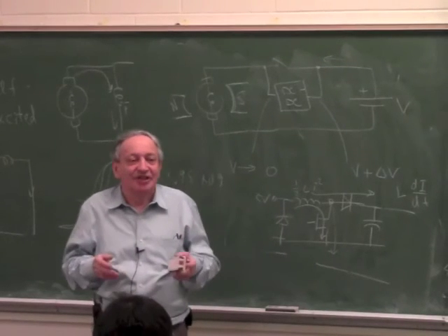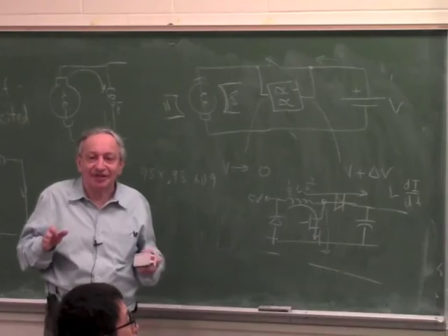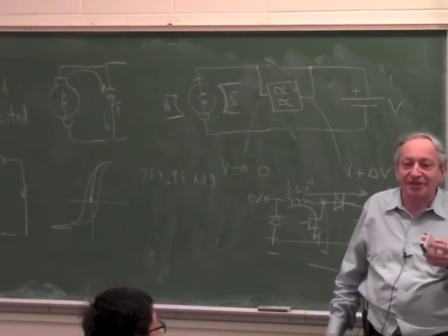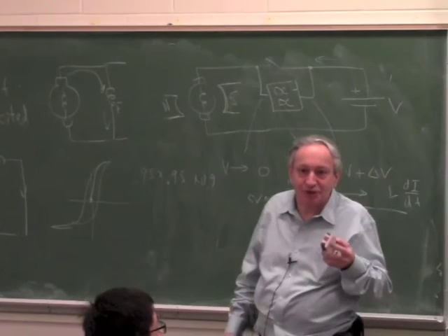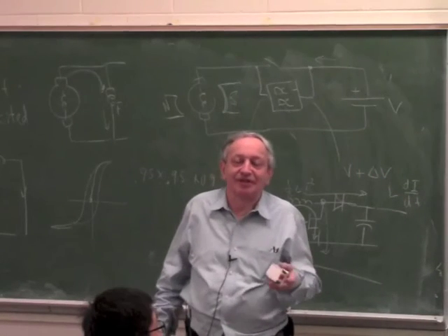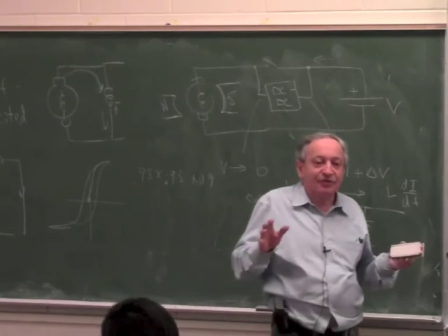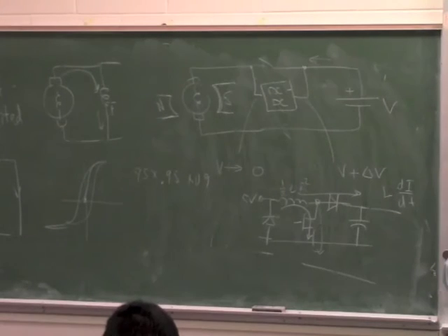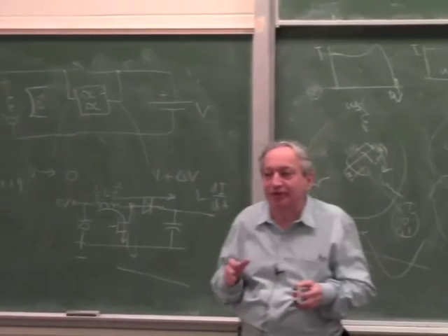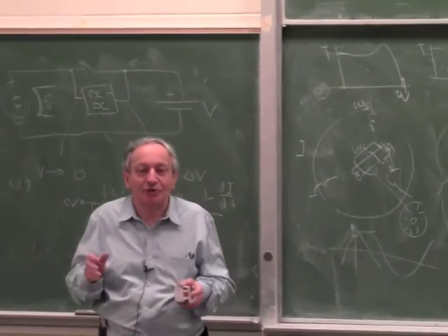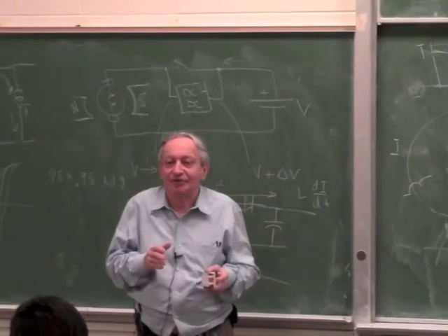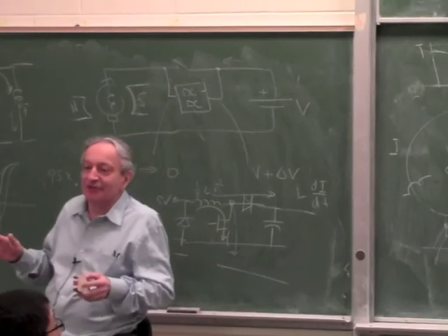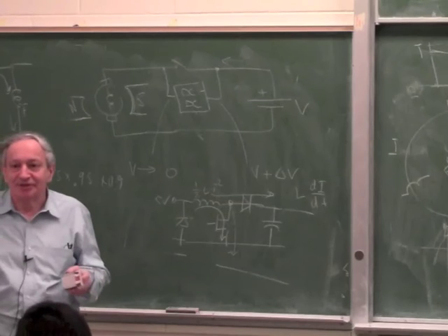And basically, for any other servo system which is not electric, if you understand how an electrical servo system works, you can easily make the conversion between electric and non-electric. You have to remember that what's called current in an electric servo is called flow in a fluidic servo, and what's called voltage in an electric servo is called pressure in a fluidic servo. So now you can use the same equations.